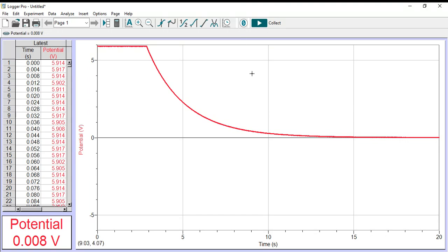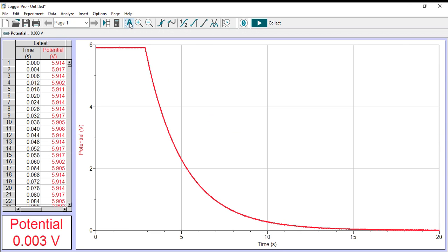So there's our graph, and you'll see again on the instructions that I can use this option up here to auto scale the graph. If I click that one there, then you can see that there's our capacitor discharge curve. You'll see that on the analysis, it suggests that step one is that you should sketch that graph there. So you may want to pause the video at this point here so that you can sketch that graph there.